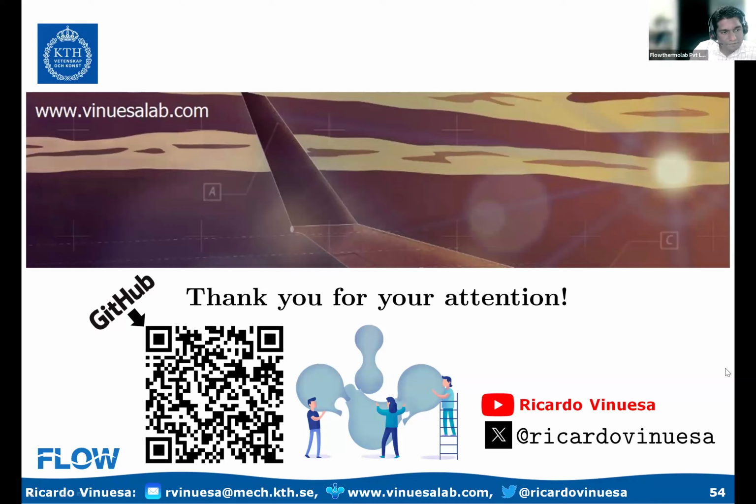Another question is, does advancement in machine learning bring about better methods to do turbulence modeling in CFD simulation? Yeah, I think so. Basically, what I see most potential is in reinforcement learning because you can really dynamically adjust your model to the instantaneous state of the system. There is quite some nice work also on computer vision, on being able to identify patterns and structures in the flow that may help inform your models. And again, the challenge is the generality. But I think things are going quite quickly forward, and I see quite some progress coming this way.